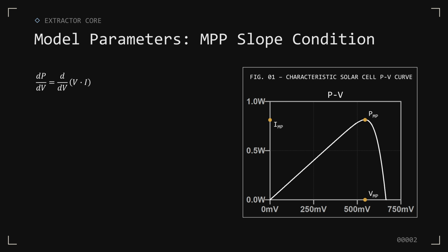So let's start with the equivalent solar cell model at the short circuit point. If we apply KCL to this circuit, we get the expression where IPH equals the diode current plus the current through the shunt resistor plus the load current, which in this case is the short circuit current. Then, if a small change in voltage is applied to the output, say by changing the ideal short to a near ideal short, the currents through all of the branches change slightly.